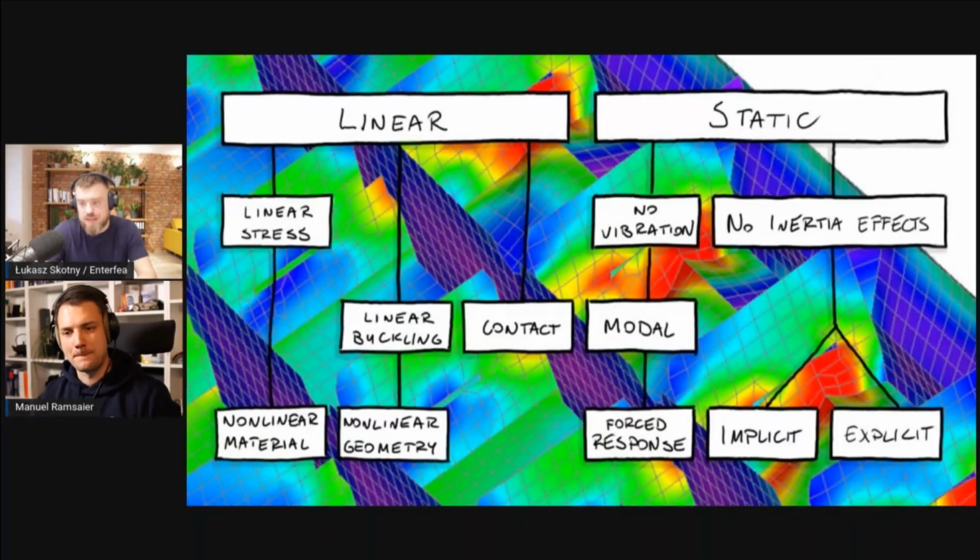Yeah. But still being careful about what you assume in your models, whether the connections are tight or not. Those are the things that can make or break your analysis, really. And to me, as a structural engineer, that's a scary concept. Because I fully know that when you're doing the design, you wouldn't really be able to tell how this works. Right. Yeah, you just can't.